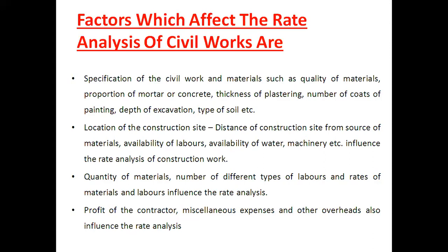That means to change the material. Now you are going with 53 grade of cement, which has a higher cost as compared with the 43 grade cement. Not much more difference is there, but a slight difference is there between the two cements. Your 43 grade is around 270. In bulk quantity again you will get a lower price, and 53 grade is 280 plus, definitely around 300, 310 it may also be, because cement rates also change daily.